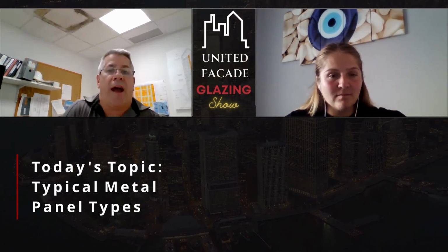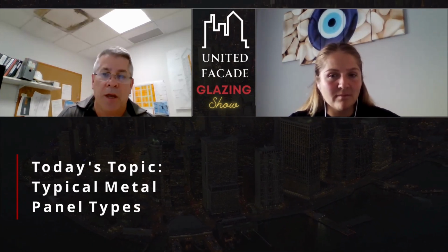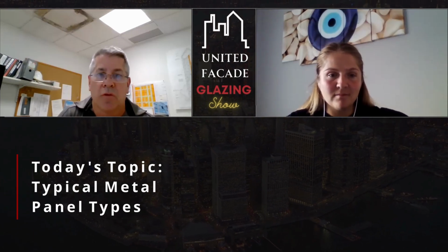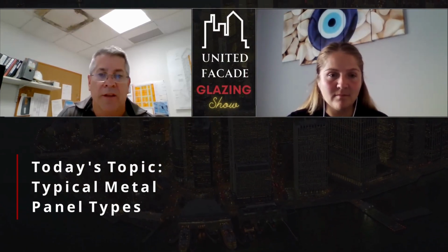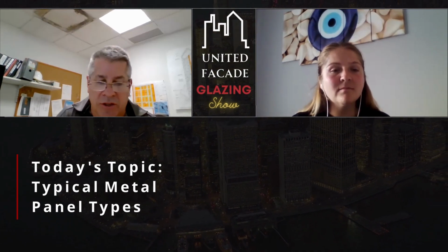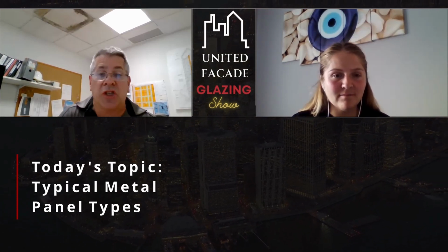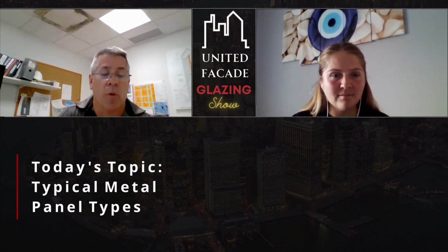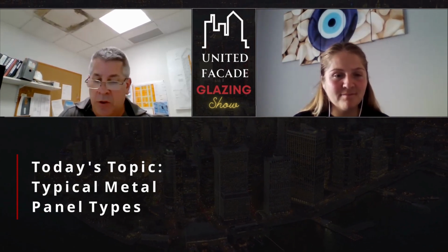The manufacturers each have their own independent installation details. Some people will make a return corner on it and add a clip onto it, and you screw the clip to your wall. Others will interlock, where panel 1 is hung onto panel 2, panel 2 is hung onto panel 3, and they interlock, and then you screw through flanges. So each manufacturer has different ways of attaching it. But again, it's a fairly standard, straightforward system that will cover a lot of square footage on a building fairly quickly and fairly cheaply. So it's a very commonly used product.